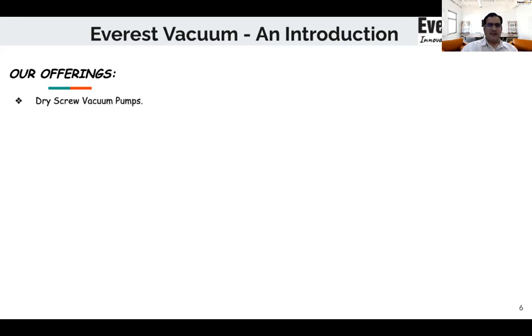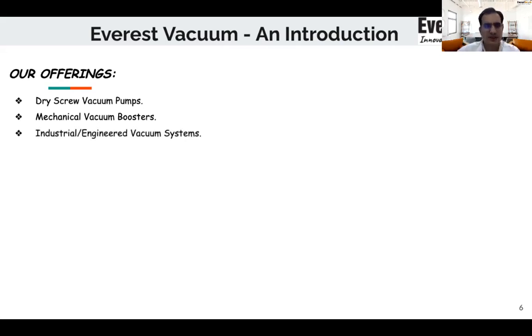So our offerings are dry screw vacuum pumps, mechanical vacuum boosters, industrial engineered vacuum systems, liquid ring based semi-dry vacuum pumps. Why we call these as semi-dry? Because we focus on closed loop recirculation. We don't consume even 1/10 of water which is being consumed in conventional liquid ring based technologies.